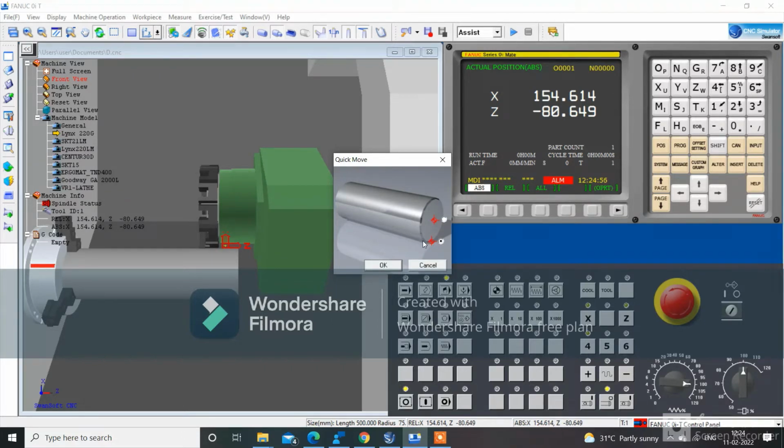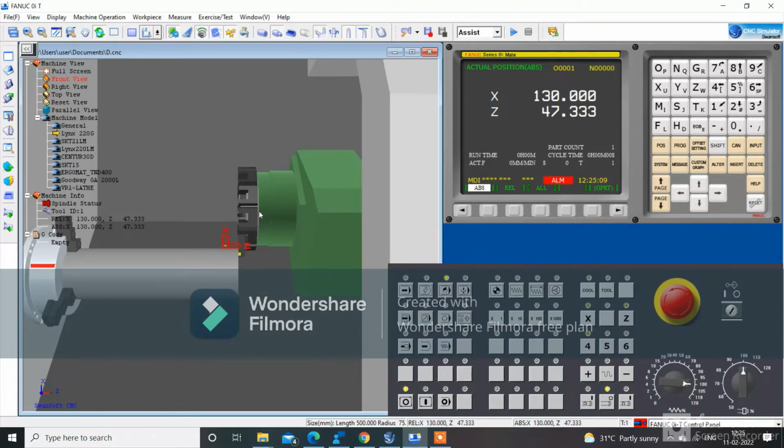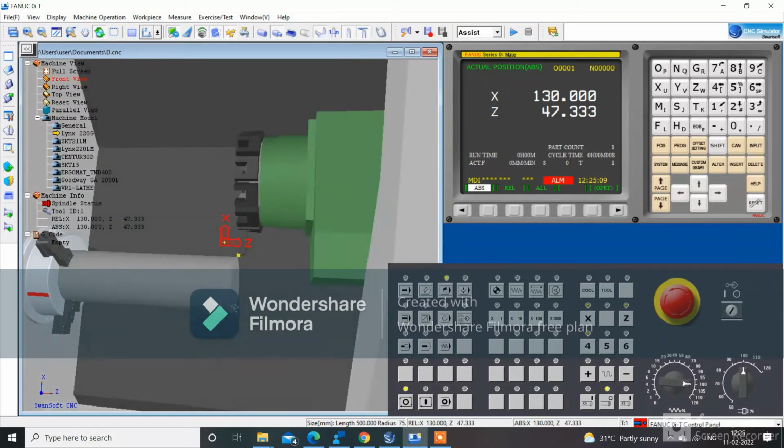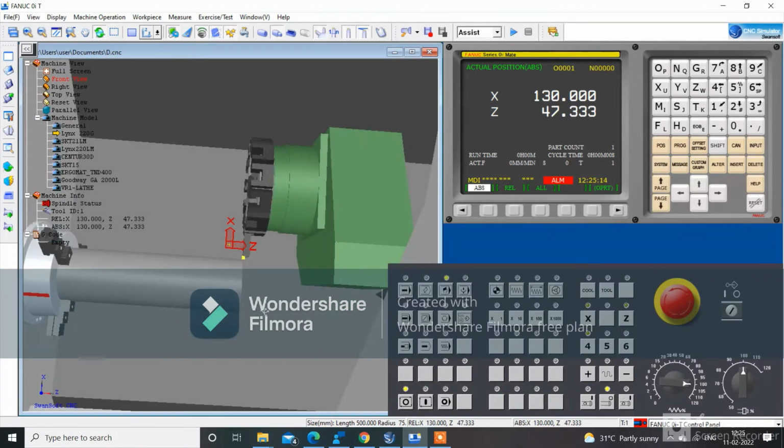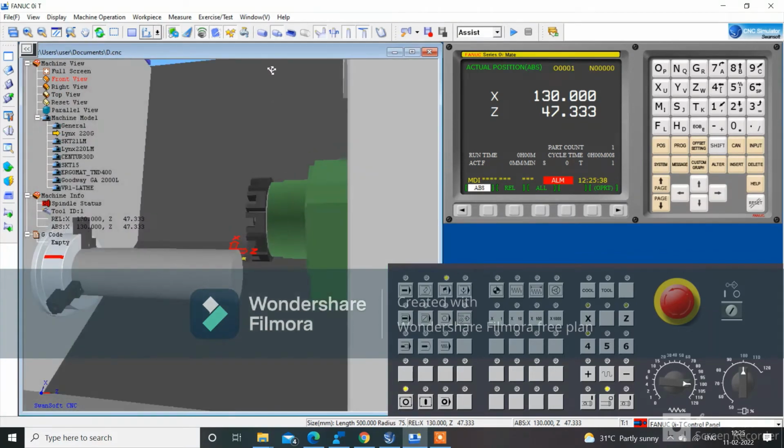We have to bring the workpiece and the tool closer, because we can bring it to the tip or we can bring it to the center of the workpiece. Okay, so it's aligned there. As you can see here, again, if I show, it will be the same. Movement will be there because the workpiece and the tool are in contact now. Not in contact is after the rapid position. It's close together now. So we are done.